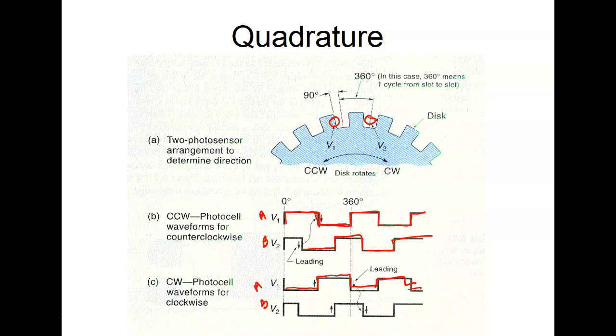The problem we have with robots is that if you lose power to your counters, the robot doesn't know where it's at anymore. So what you'll find out about robots is they have batteries that we have to replace. And what those batteries do is they keep the count on those encoders. So if you ever let those batteries run down and you turn off the power to the robot, then you're going to lose your count, and then you'll have to remaster the robot. So it's usually part of the preventive maintenance schedule where they go out to all these robots and swap those batteries out. If they do that at Bros, they go out and change the batteries every once in a while. That happened the other day.